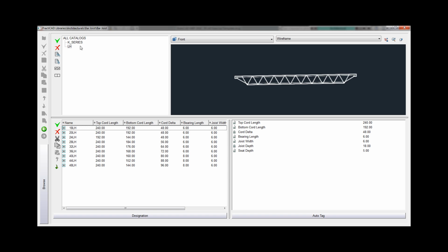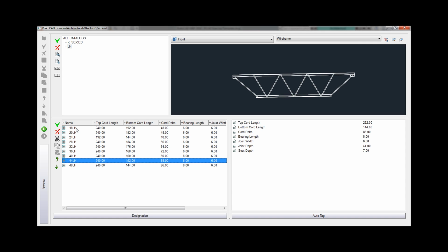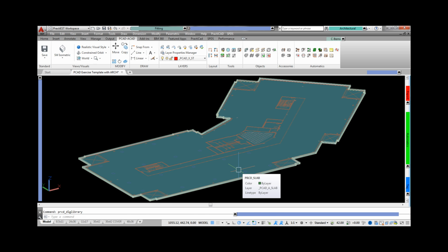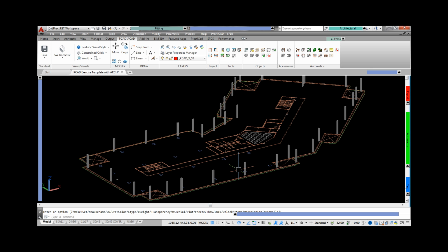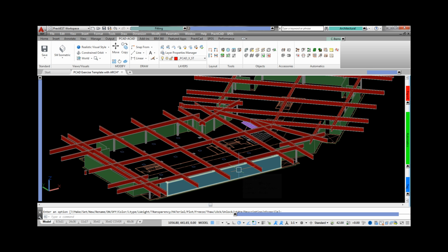You can even create libraries of parametric bar joists. Here you can see as we run through a standard K-series catalog. Notice that everything is in your control, including the length, seat heights, and delta for adjusting the webbing. This way your model will have a true representation of what you can expect in the field. Drawing with PractiCAD architecturals is easy to do and can really be handy when you're still working with 2D backgrounds.